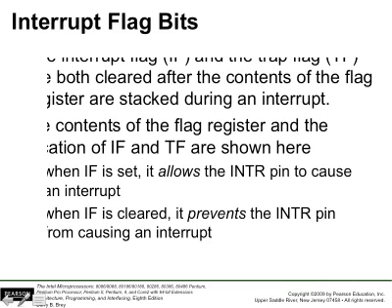The meaning of these two flags is that the interrupt flag is the one that we use to enable or disable external interrupts. It's INTR. Remember, INTR is the interrupt pin that will be asserted by the external devices, oftentimes a programmable interrupt controller, and that's the pin used by the device to notify the processor we have an interrupt.